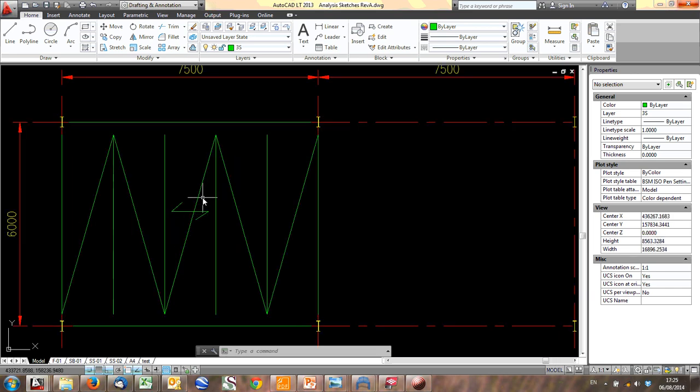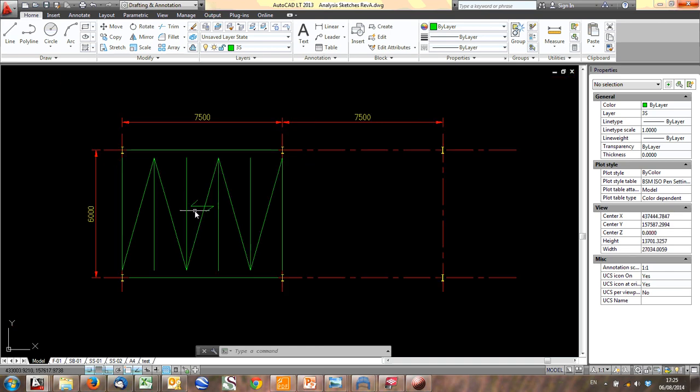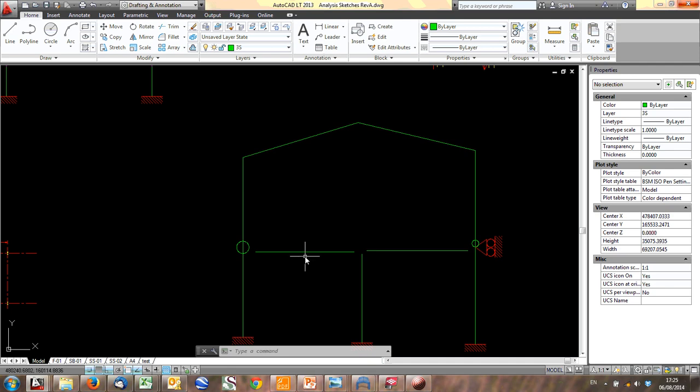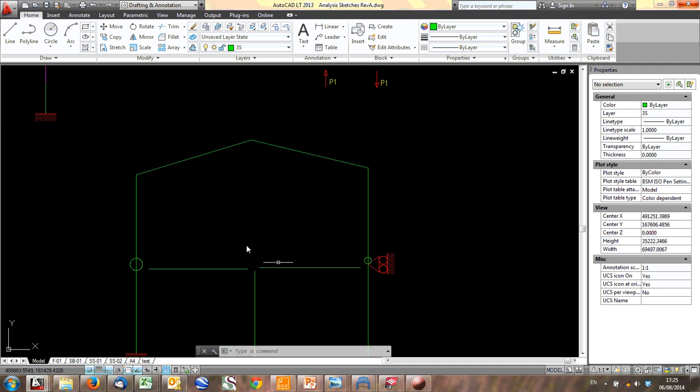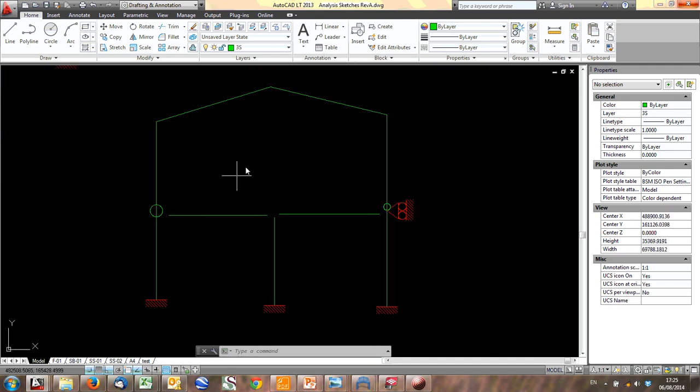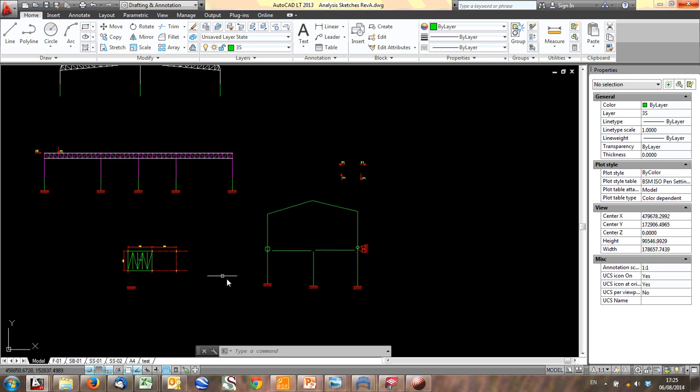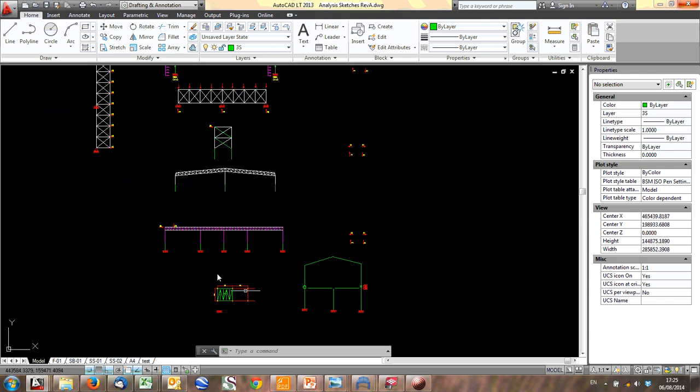One thing you must remember is you have a look where all the load goes and where can you take it to where it can be efficiently handled. So you can add pieces to your structure, and you must add pieces to your structure that you can then transfer it. So especially with this deck, you only need to add one brace each side, and you stabilize all these portals. So it's much more efficient to do it this way than to design each frame as full moment resisting. So there are various different ways you can consider that.